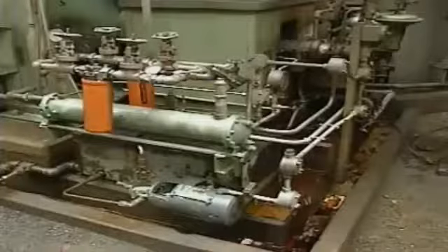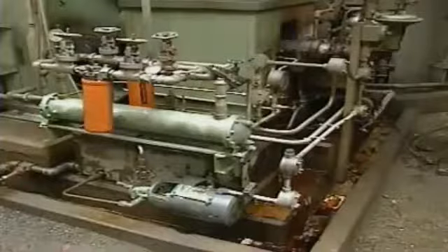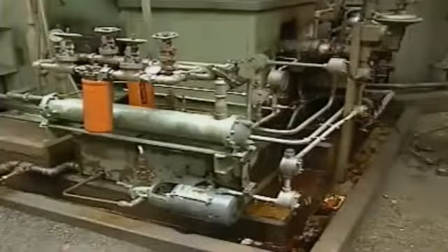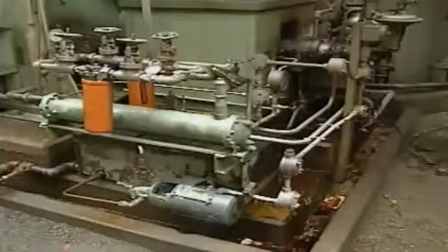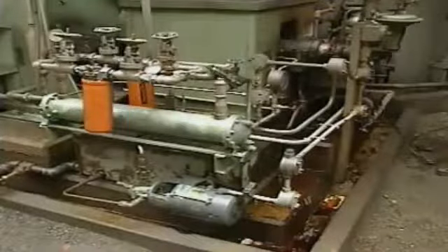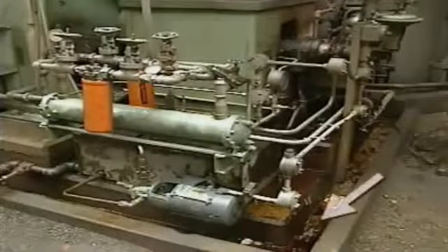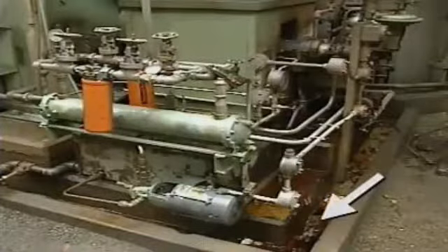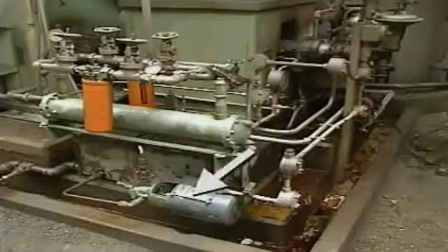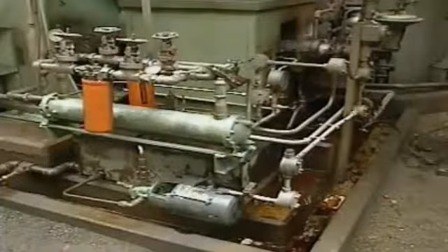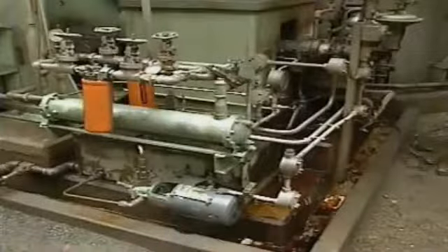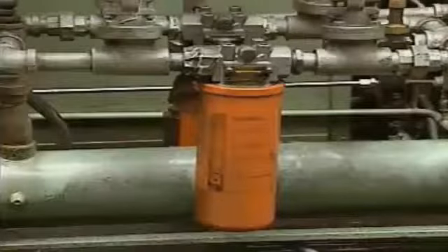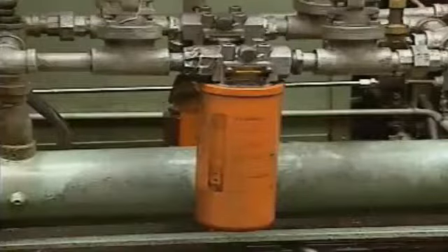Another type of oil lubrication system for sliding surface bearings is a force feed system. This type of lubrication system is used when a pressurized feed to the bearing is required or when it is necessary to keep the oil filtered and cool. In a typical force feed system, oil is stored in a reservoir that is separate from the bearing. A pump forces the oil into the bearing. After the oil has passed through the bearing, it is collected in the reservoir so that it can be pumped again.